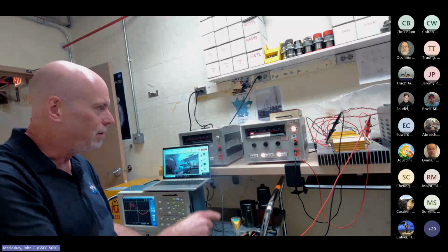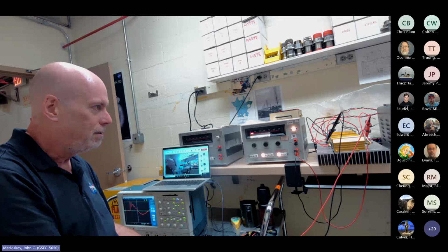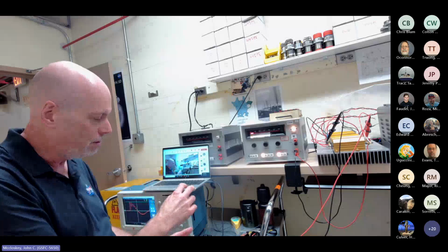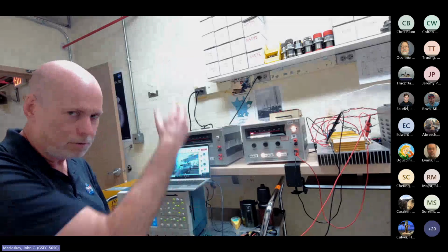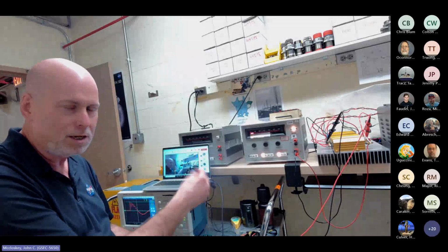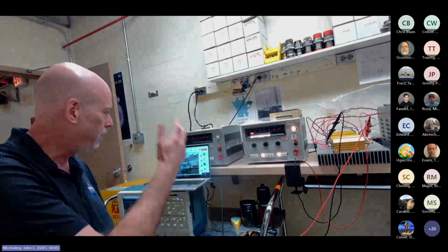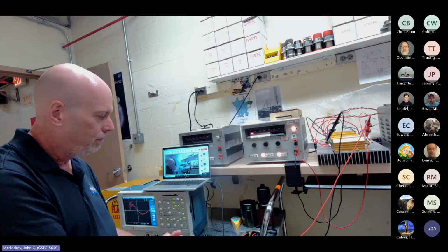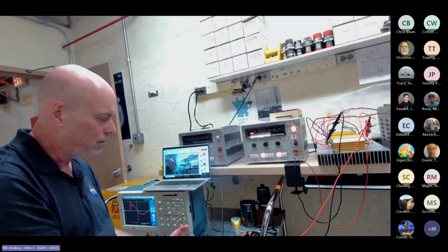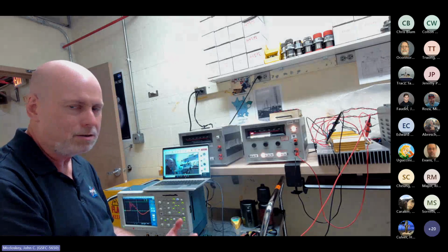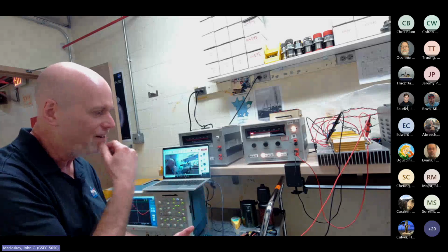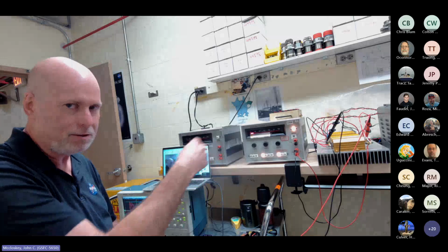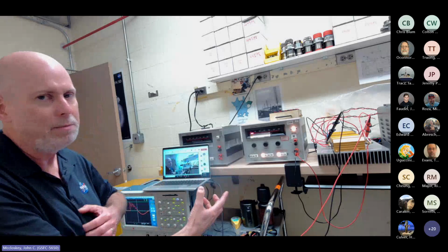But the positive going transient does have some potential stress or damage concerns, right? If you're going from 30 volts to 60 volts, or even if you're applying a 2 times or 3 times bus potential, you're taking it up to 100 volts. Yeah, it certainly can pose a damage concern, but it's a design driver, right? Those front end components need to be rated or derated to handle that as their maximum potential. That comes up all the time.